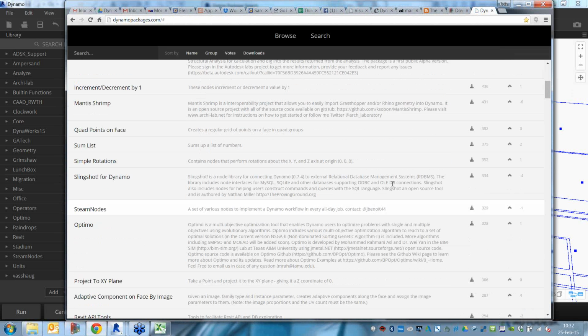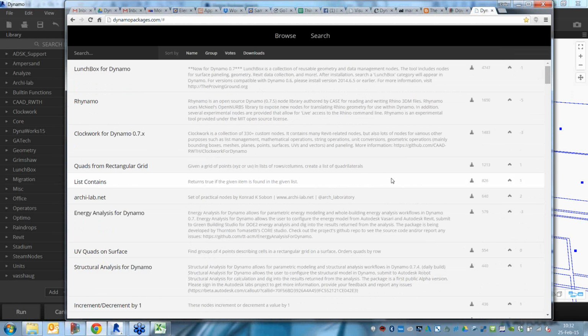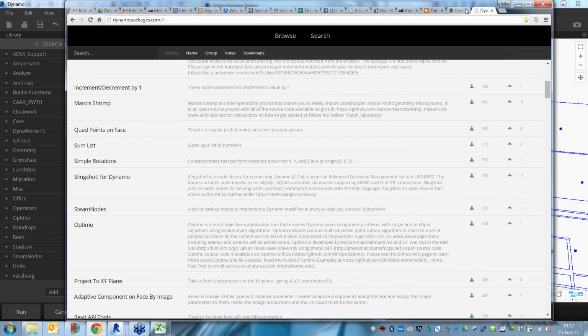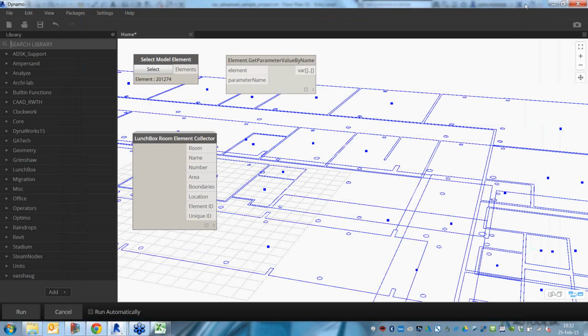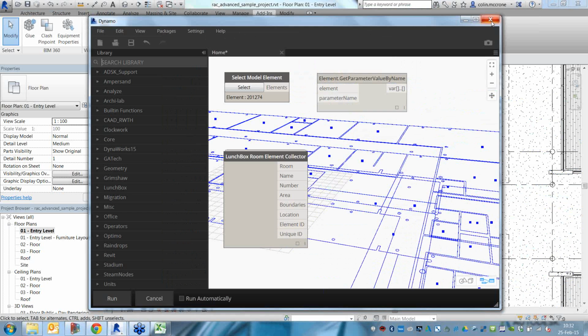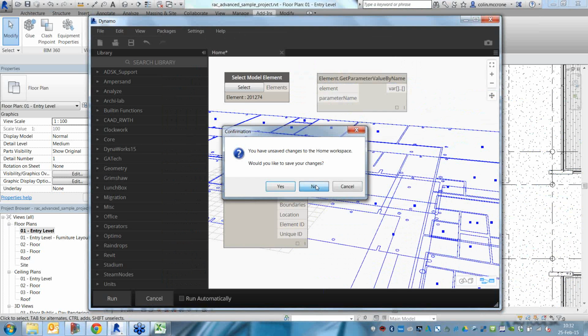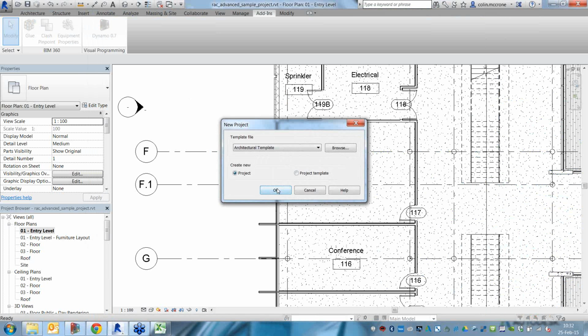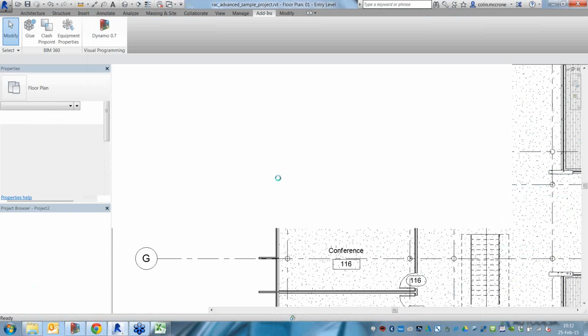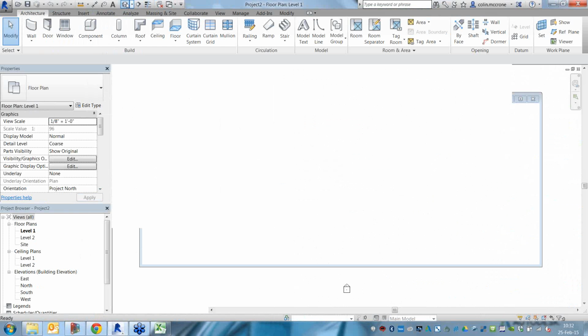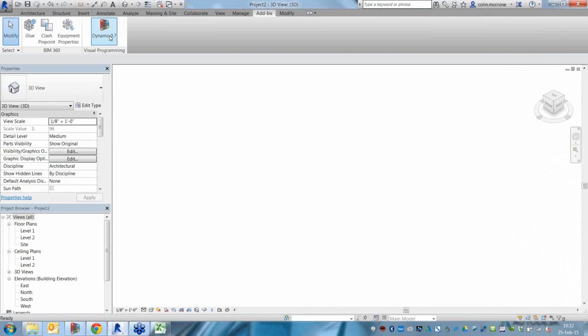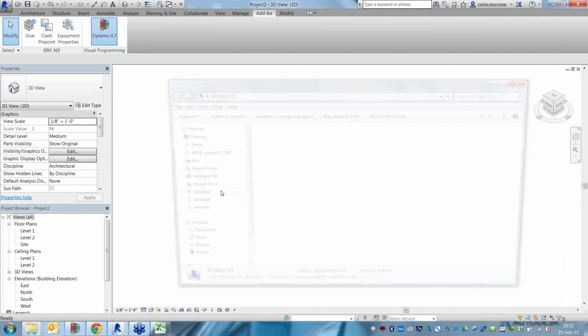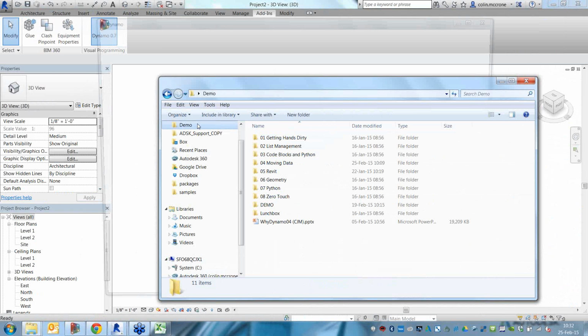If Revit doesn't really know about them, you can read that information into Revit using Dynamo, using that Excel link that Colin showed before, or just reading a text file. Then you can create rooms that haven't been placed yet. They're able to be placed, and they have the right information, like the room name and number and description, and then place them manually inside of the application.